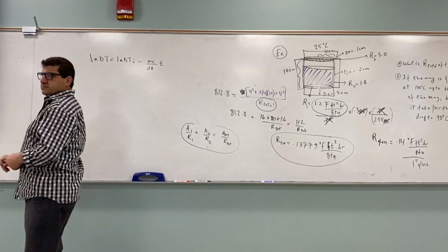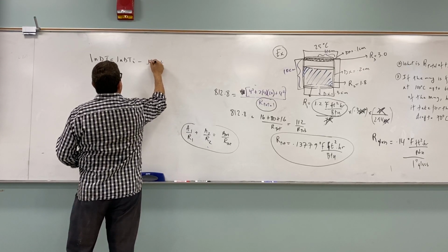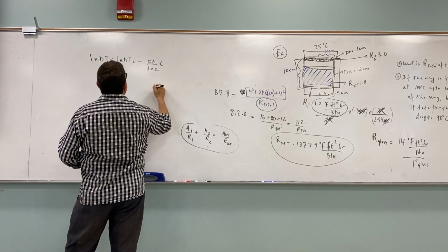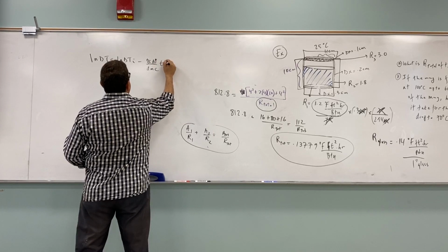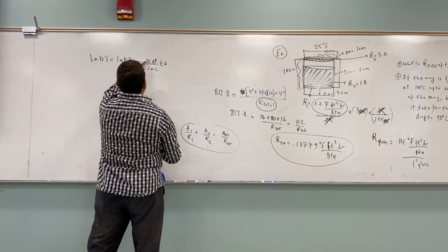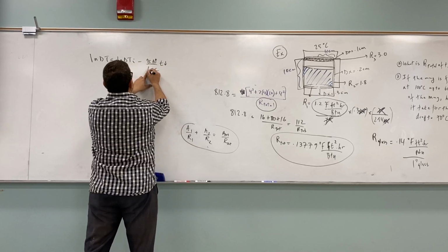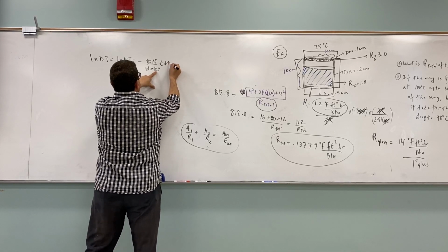Oh, it's K over DMC. So that means the bigger the conductivity, the bigger the surface area, the less time it takes to cool. The thicker it is, the more mass it is, the more specific heat it has, the bigger the time.